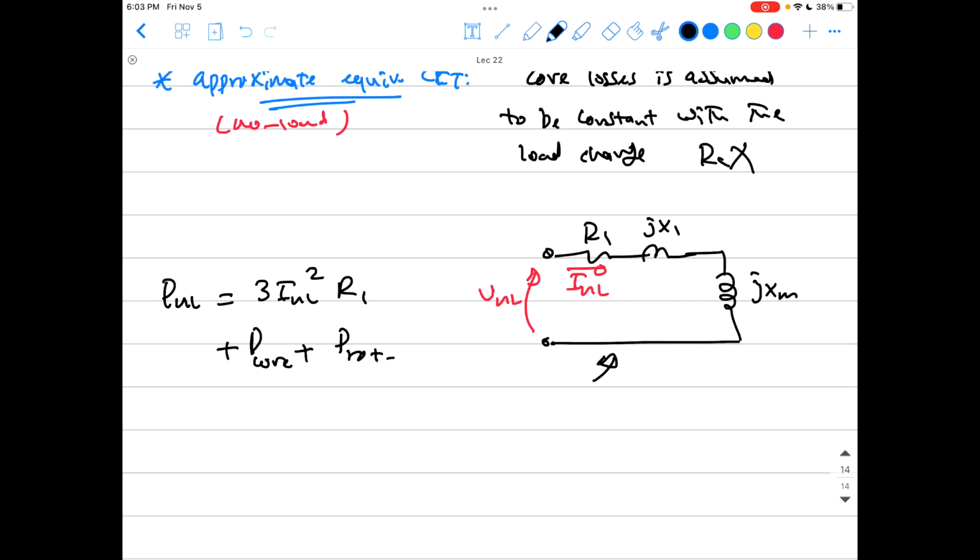That's the thing. If you remember when I illustrated this in the last lecture, the equivalent circuit represents all of the losses we have in the machine by resistances except for the rotational losses. That happens in the exact equivalent circuit, where you have RC representing the core losses, but you don't have anything to represent the rotational losses, so don't ignore it. It's there, but it's not represented in the equivalent circuit, okay?